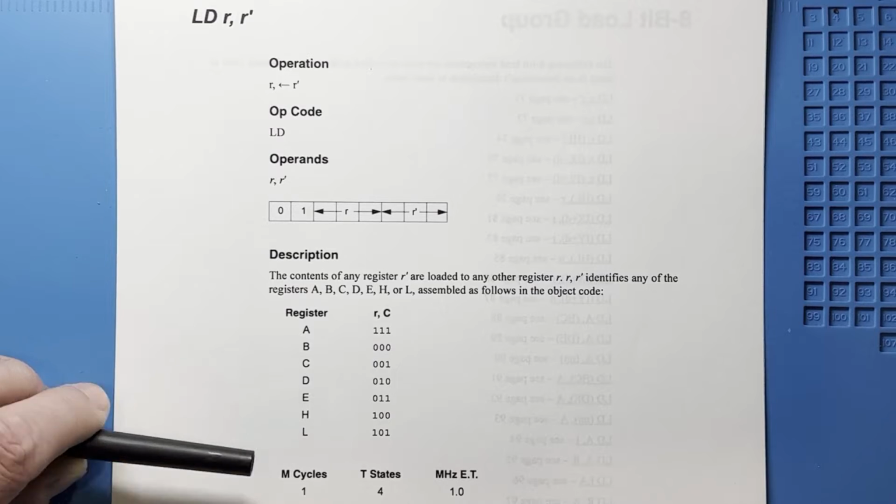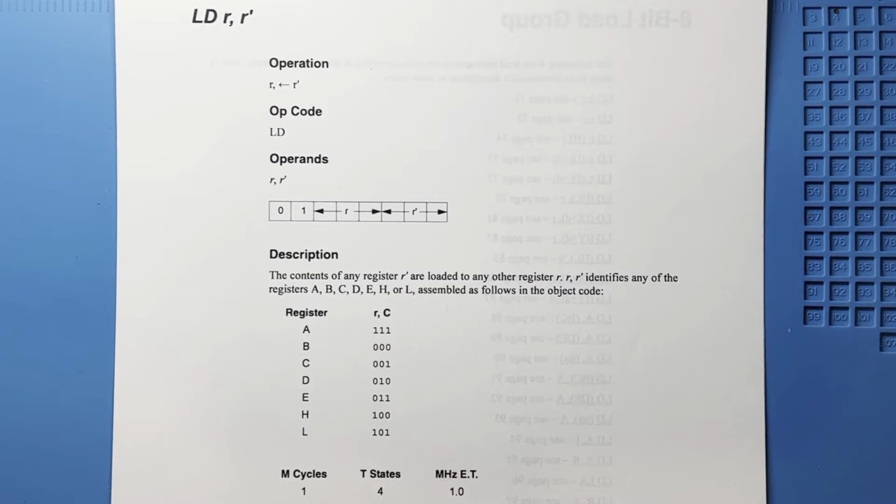fewer clock cycles. So the first step in this execution is to put the current address from the program counter onto the address bus. Then it does a memory read to have the memory put the opcode on the data bus. The CPU then reads it from the data bus and decodes the opcode. It then increments the program counter. If it can, it will then execute the command in the first step, as with the example of this command. This is referred to as the M1 step.